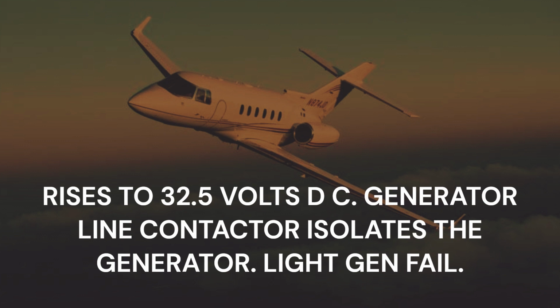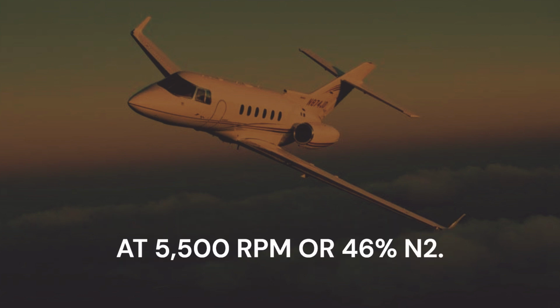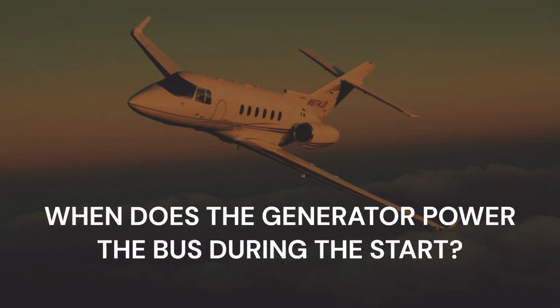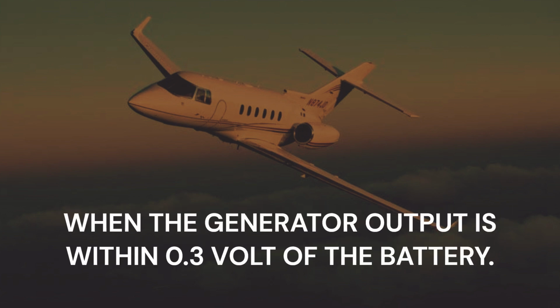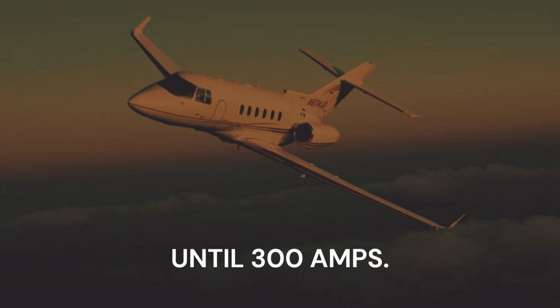Light: gen fail. When does the generator disconnect during start? At 5,500 RPM or 46% N2. When does the generator power the bus during the start? When the generator output is within 0.3 volt of the battery. Up to how many amps can a generator power the whole DC system? Up to 300 amps.